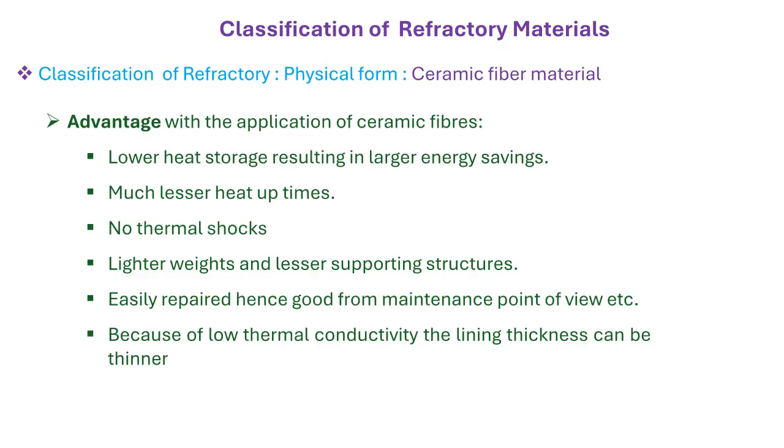Sixth advantage: thinner linings. Thanks to their excellent insulation, ceramic fibers achieve the same performance with much thinner linings. This gives you more usable furnace space and even faster heat-up times. All these advantages combine to make ceramic fiber an attractive choice for modern furnace design and operation.